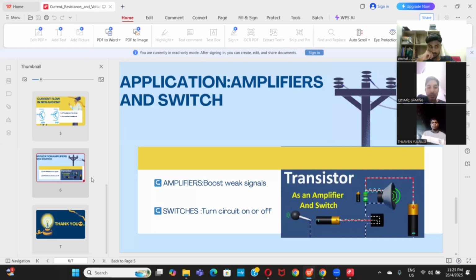So the first question is, what happens if you mix up the collector and emitter when using a transistor in a circuit? The transistor may not work correctly. It could have very low gain or fail to operate at all. Some damage is possible if high currents are involved.